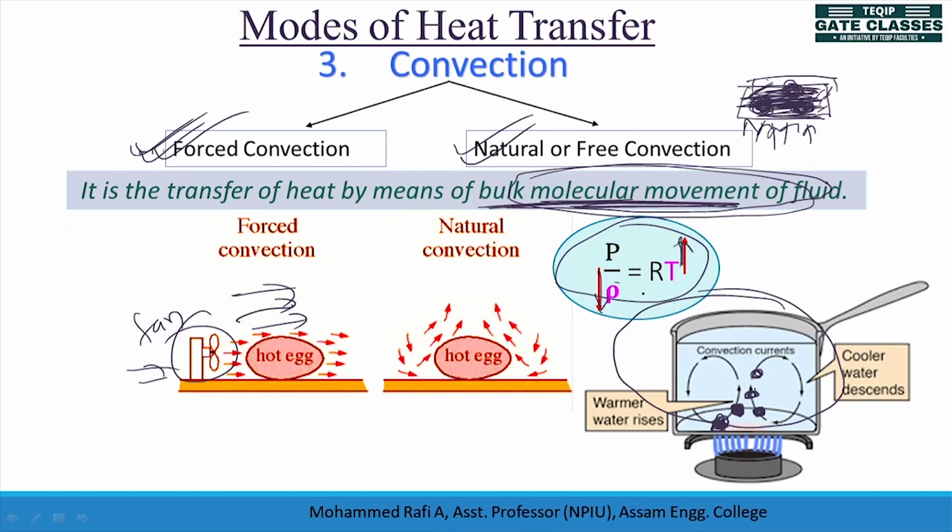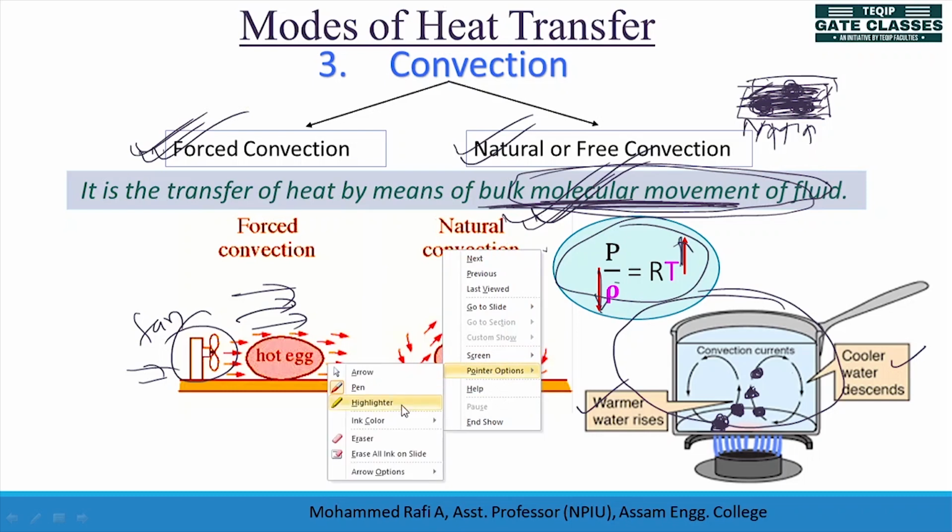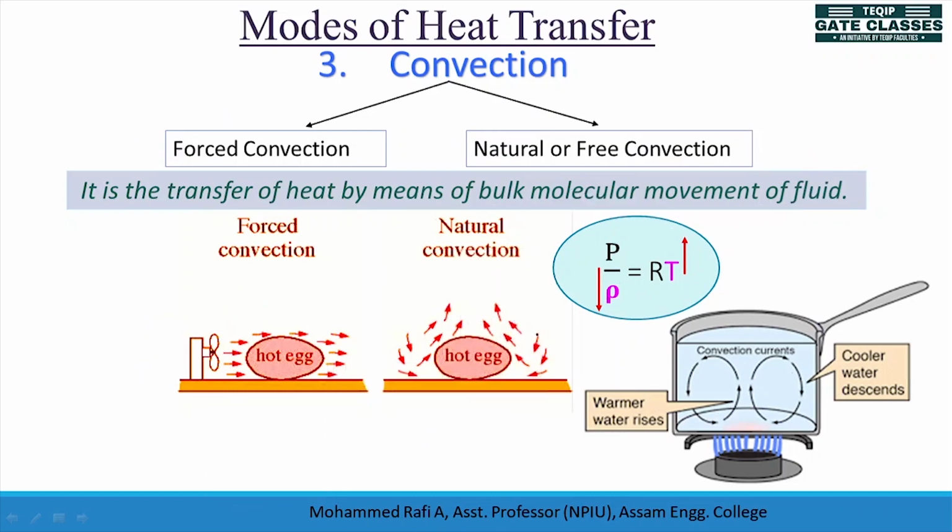So it may not be applicable for all fluids, but for better understanding, I am just quoting this expression. So when temperature is increased, density goes down. So the lighter molecules go up, heavy molecules go down. So what is the lighter molecule here? Warmer water molecules go up, cooler water molecules go down. So yes, there is bulk molecular motion. That is why we will call it convection. We will not call it conduction.